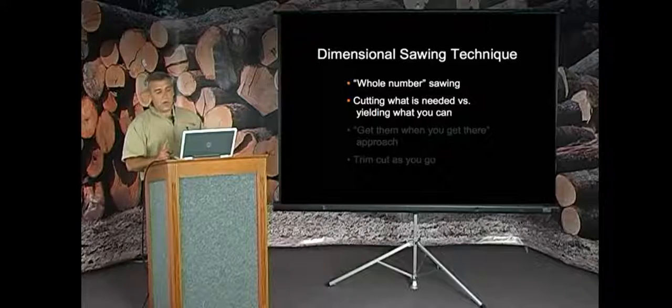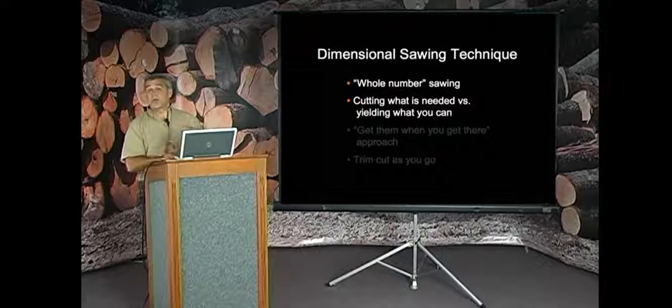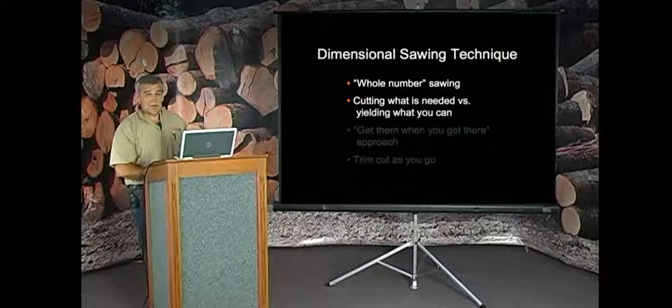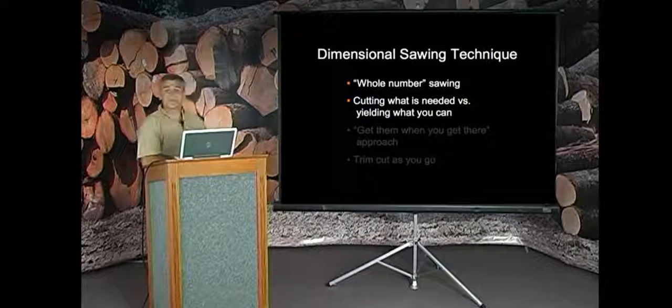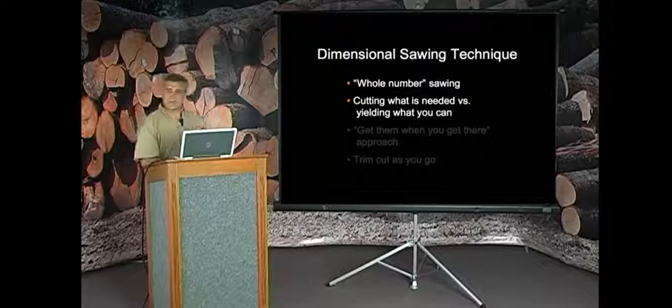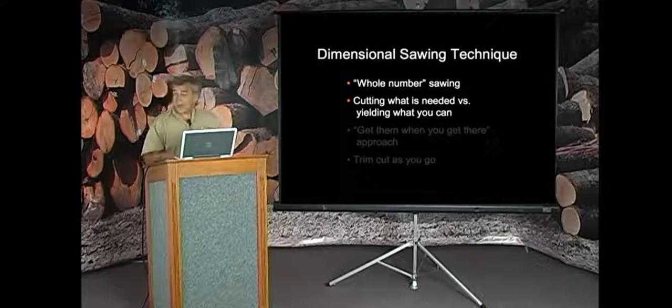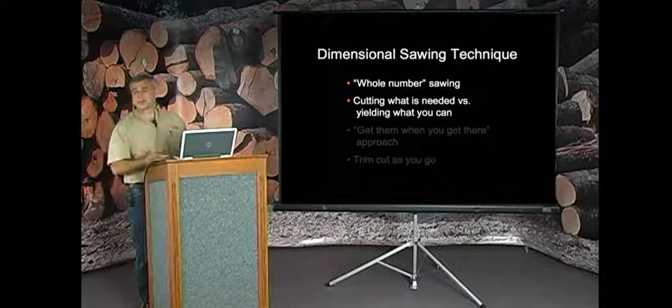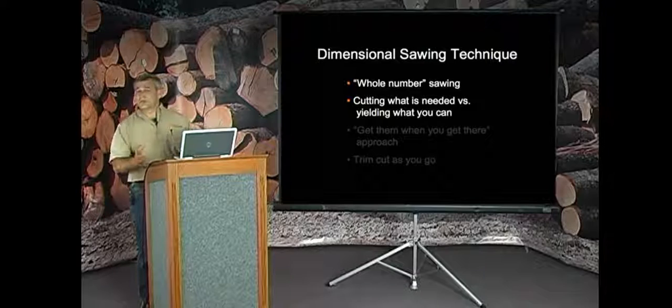The neat thing about whole number sawing is that you're really going kerfless. Your 1-inch lumber isn't an inch. But you know what? Your plywood sheeting products and so forth today aren't an inch either. They're somewhere under 3/4 of an inch. But if you drop from 11 to 10 and make a cut on a Wood-Mizer mill, you're going to get a board that's a plump 7/8. It's going to be just slightly over 7/8 of an inch. Will that work as a sheeting product versus a store-bought product that's under 3/4? Works just fine.